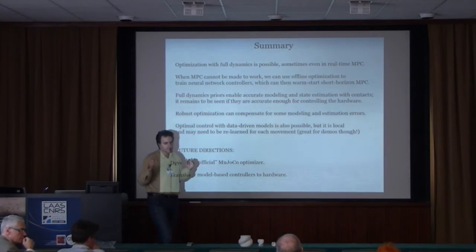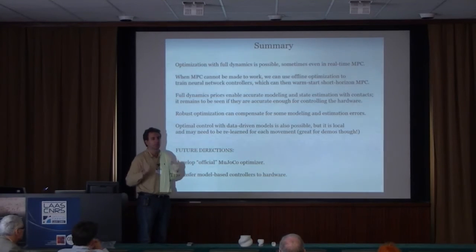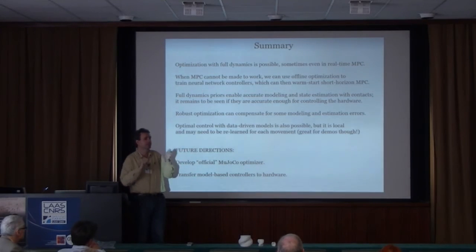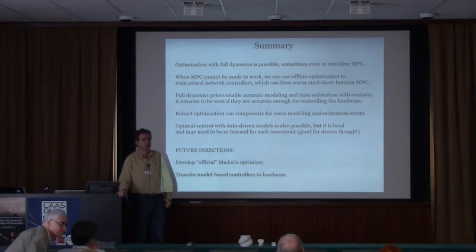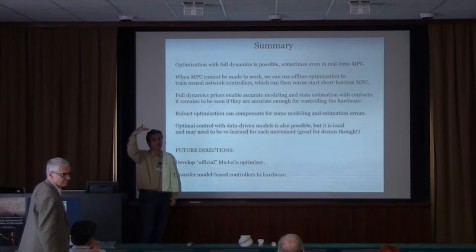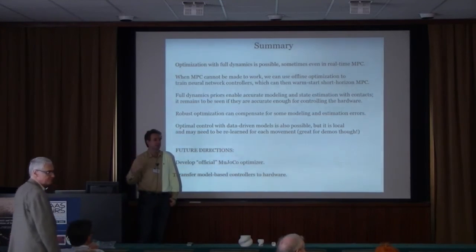In terms of stability, yes, sometimes you want to take something like angular momentum or some such quantity and penalize it, put a quadratic on it. So these features that I talked about, that's where human insight comes in. You try to guess what are the things that are likely to be important, and you suspect that you have to keep them small and throw them in there. And then after you make that guess, it's a little bit of tuning weights, which is not much actually. But ideally you would start very high level, and the optimizer will discover those. And it does offline, but not in real time.